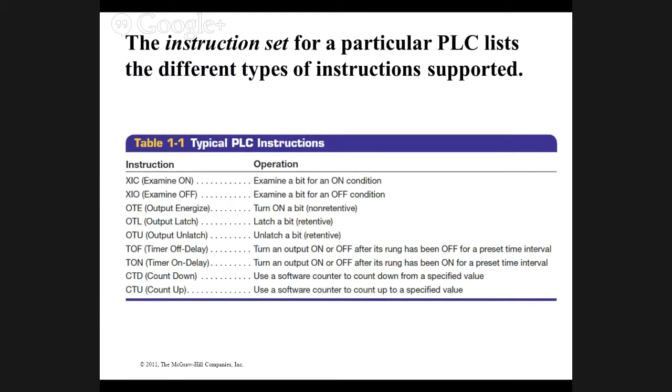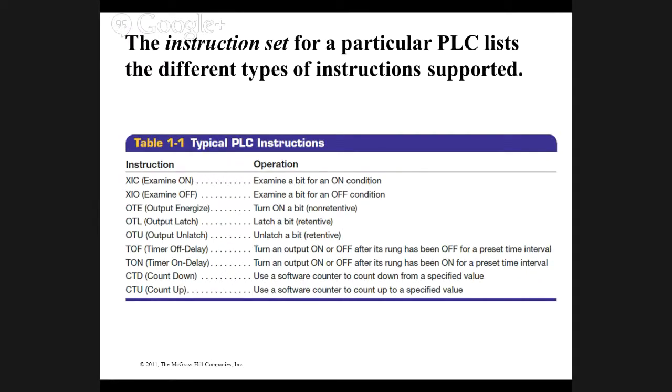So, the instruction set for a PLC is the different types of instructions supported. We have examine if on, examine if off, output energize, output latch, output unlatch, timer off, timer on, count up and count down. We're going to get into those here in a second, but I just wanted to show those to you. You'll have to memorize those. They're not too hard. Are we done? I think we are. You have to know what that means.